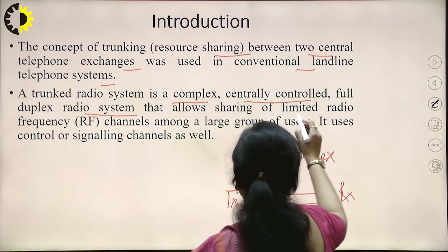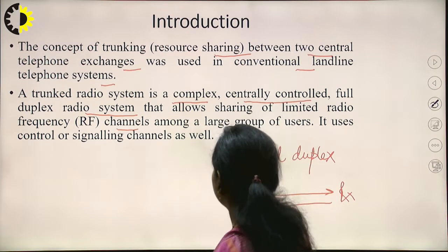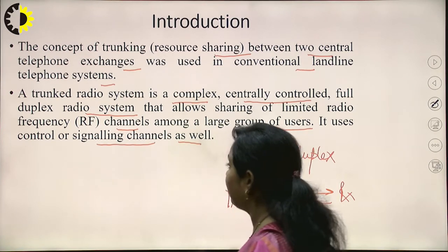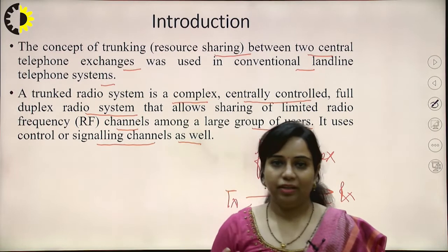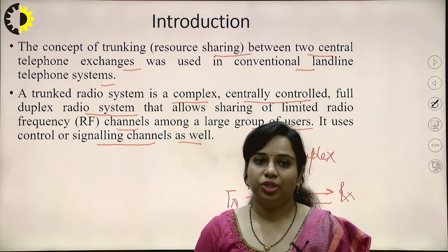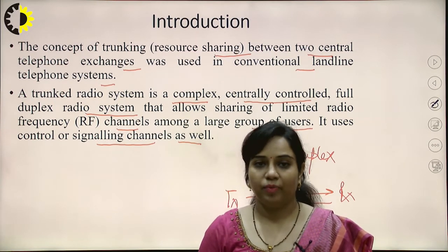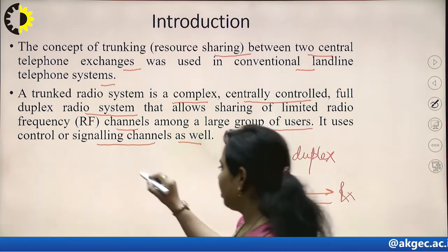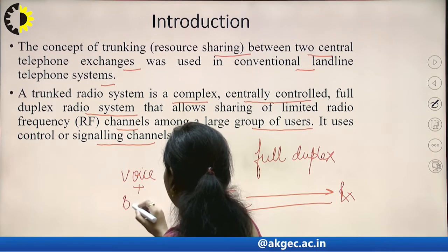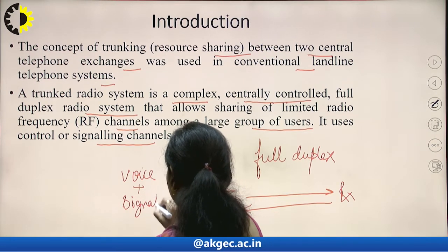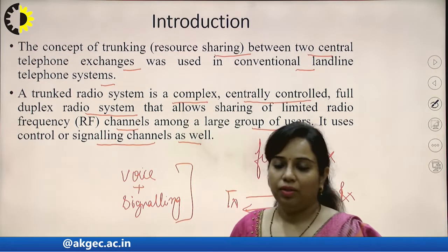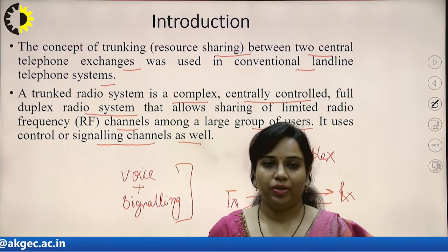It allows the sharing of limited radio frequency channels among a large group of users, along with control or signaling channels as well. So apart from sharing the resources available for a particular communication, we are also sharing control signals and signaling information along with the voice signals. This is the concept used in the mobile communication system, the trunking operation.